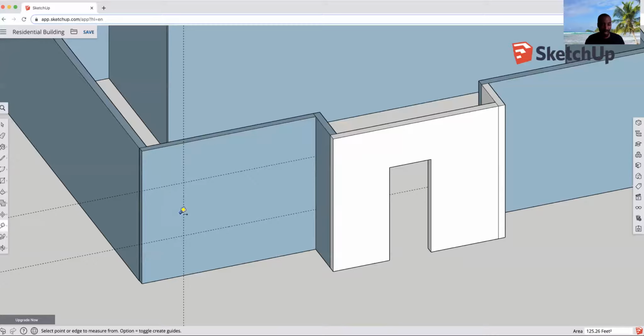All right, now how wide do I want this window? All right, I can say, all right, the width of that window, let's see. So this is 3 feet and the window goes 4 feet, so I'm going to say 7 feet across. So from here, I move across again and I'm going 7 feet, because the 3 feet plus the 4 feet for the window, that gives me 7 feet, enter. Now this area is going to be representing the window opening.